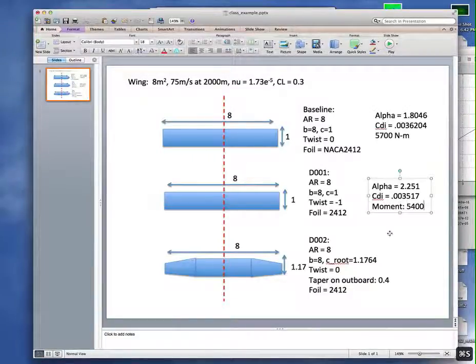Okay, I put a bending moment constraint in your design problem. Otherwise, you would just let your aspect ratio go to infinity, essentially, and have your 0 induced drag. Which is not quite true because you start going to have more profile drag, but you would have too large an aspect ratio. It would be a silly looking wing. So the bending moment constraint is going to constrain the aspect ratio of your wing, but not necessarily your span.